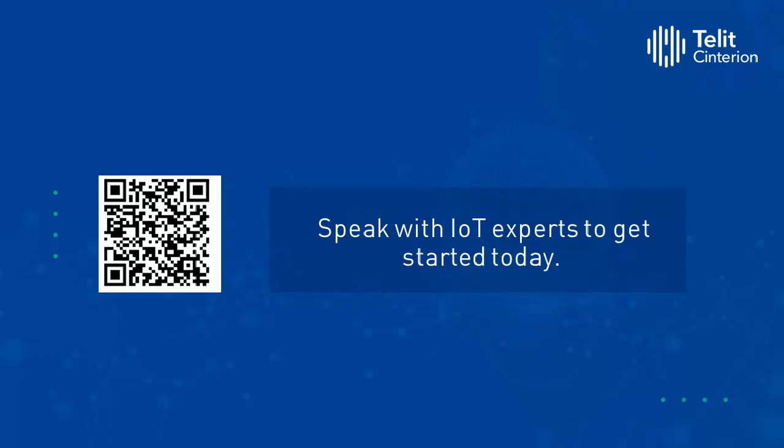Jordi, it looks like this first question is for you. Out of the challenges that you described, which would you say is the hardest? Well, from the technical perspective, and totally in my opinion, the most difficult challenge is the pin connection between the main board and the communication board, because you can do everything okay, but if you miss in this connection, the performance of the antenna can drop drastically, as we've seen in the previous slide.